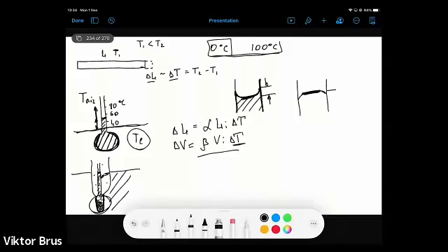And different materials provide different ranges of temperatures where they exhibit this linear dependence. For accurate measurements, obviously we want to have linear dependence, because we want to have at any point of this tube equal steps for 1 degree Celsius to have reproducible and reliable measurement. So in order to go beyond this problem, we can use the so-called constant volume gas thermometer.